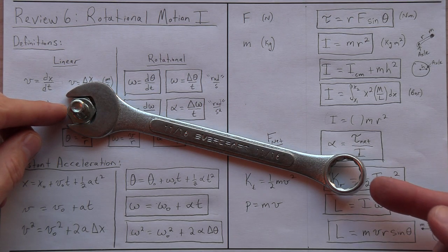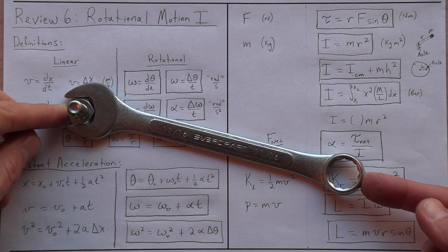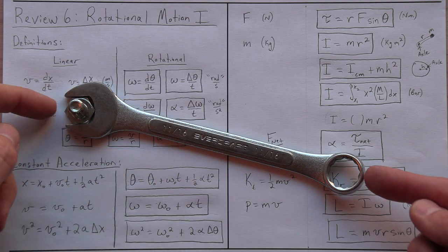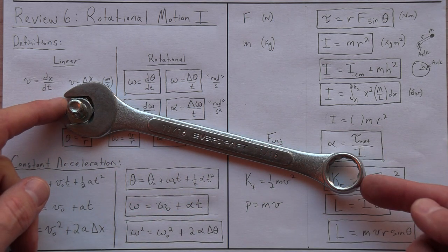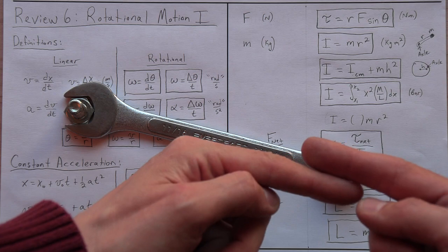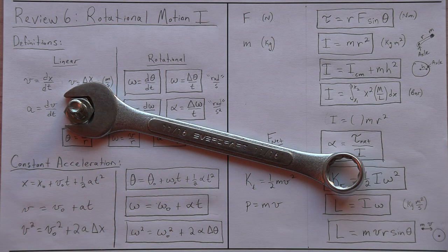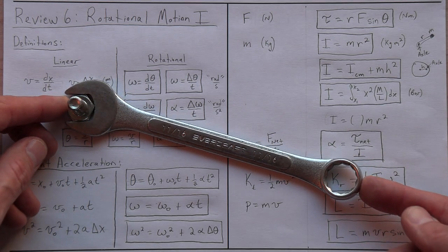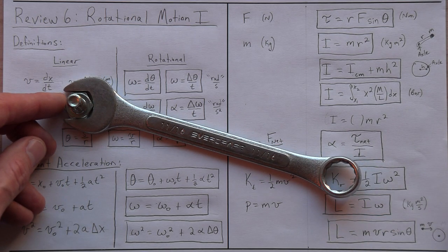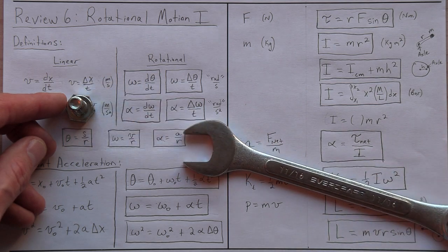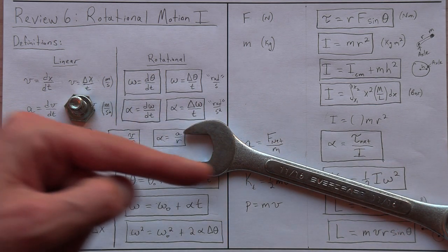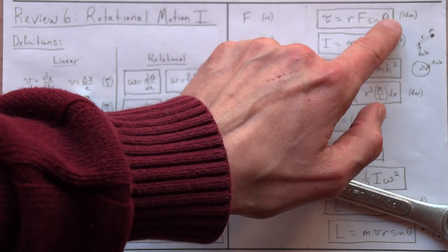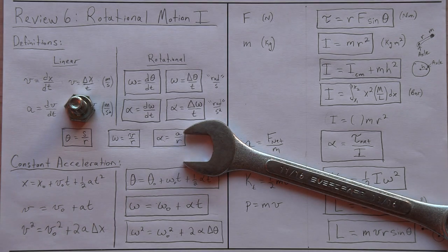For example, if I push in this way, the wrench doesn't turn. Because I have r, F, so I have a radius right here. I have a force, but theta is 180 degrees. When I calculate that, I get torque 0. No turning if I push directly on a wrench like that. Pulling on a wrench doesn't work either, right? That didn't turn the bolt because I have r and I have F in the same direction. So I plug in sine 0 instead of sine 180 and I still get 0 torque.